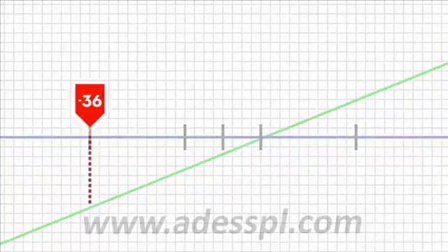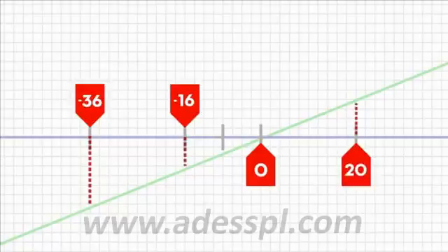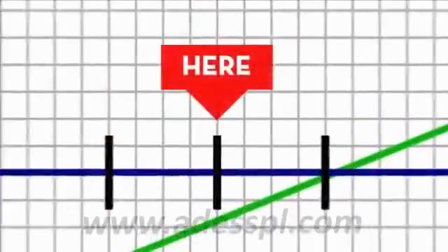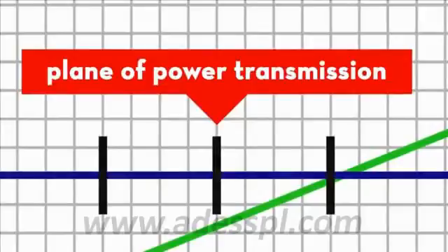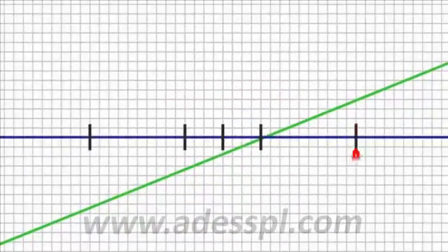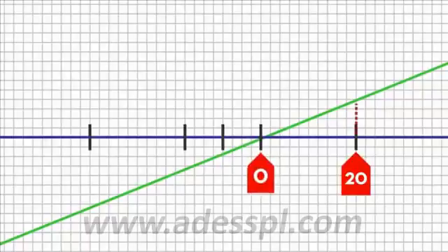From the graph, we can see that the shaft rises 20 thou between the front and back feet of the motor. The distance between the front and back feet of the motor is 10 blocks across, or 10 inches. Divide the rise of 20 thou by the run of 10 inches to get the angularity, which is 2 thou per inch.